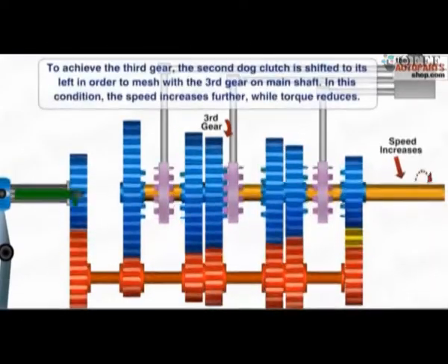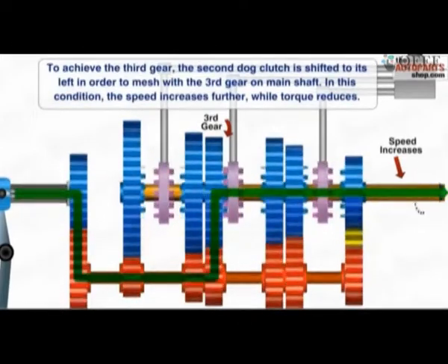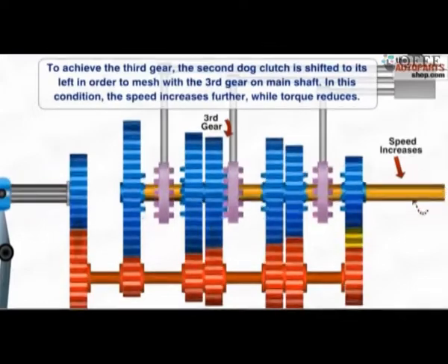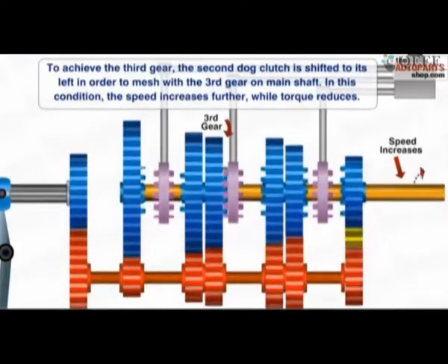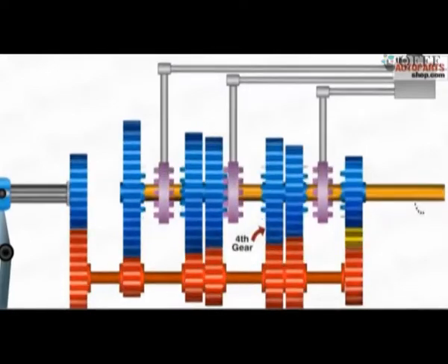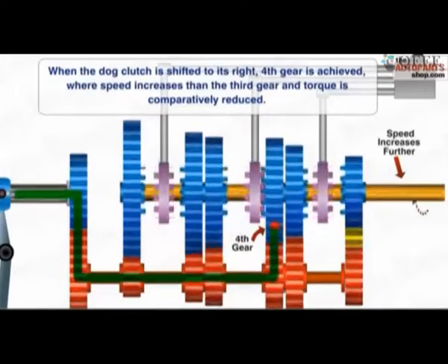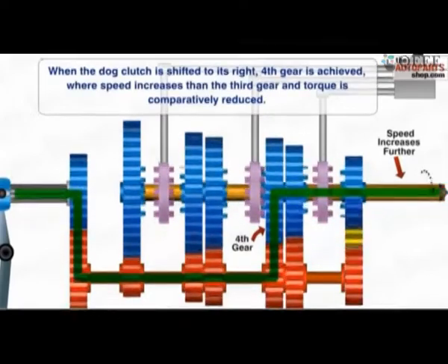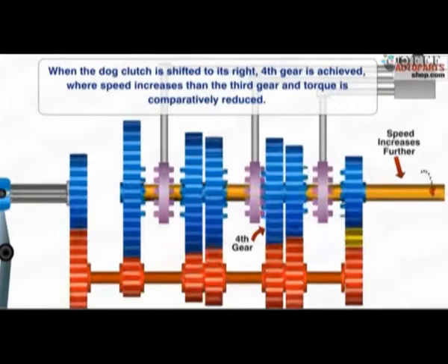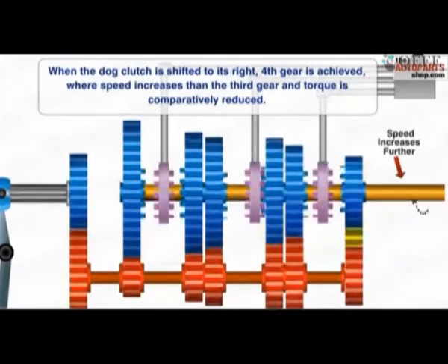What is not shown here is that you should do this operation by releasing the clutch, or by disengaging the clutch plate, because if you operate this with the clutch plate engaged, then the input power is still there. You should not try to do that, because then the system can fail, because it will break. The input power is switched off because the clutch plate is disengaged, and then you should try to move around these gears.